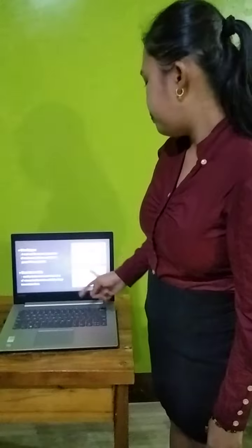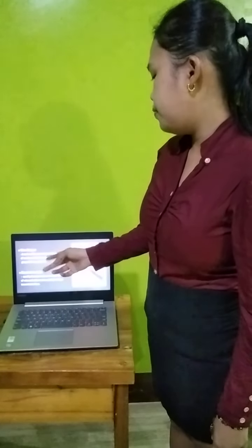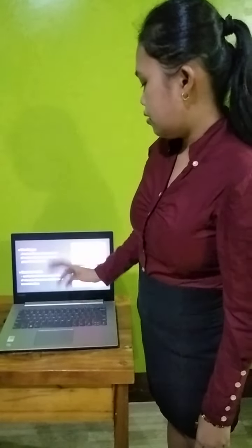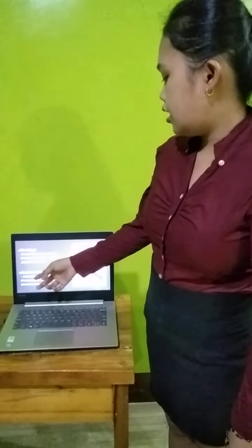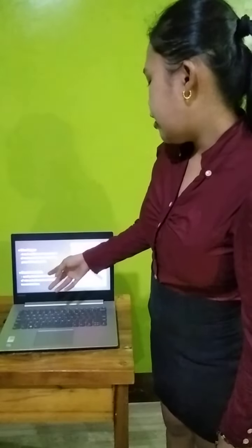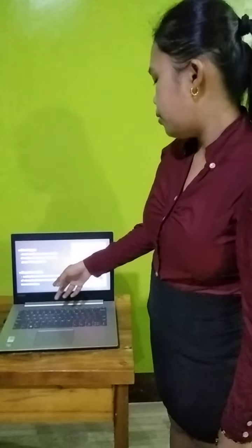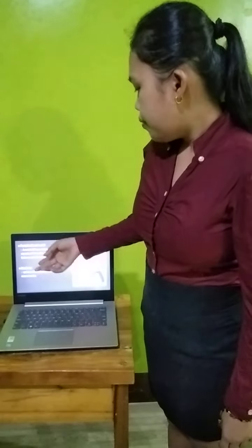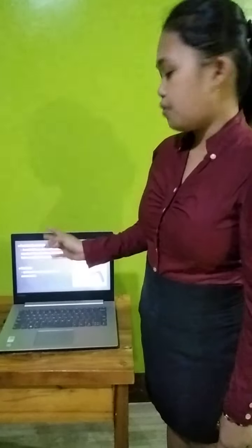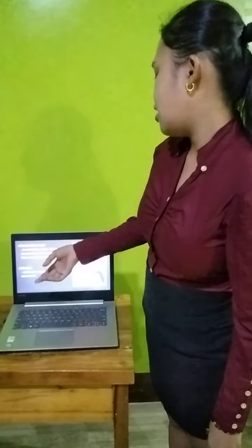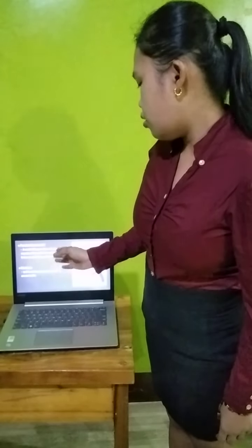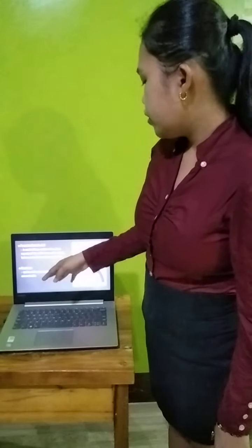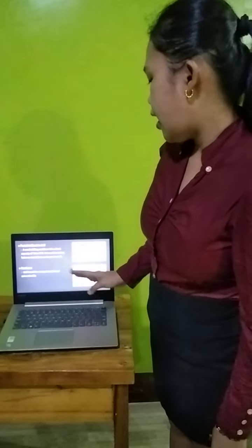Next is the wire stripper, a tool used for removing insulation of medium-sized wires ranging from gauge number 10 to gauge number 16. So next is the electrician's knife, used by linemen to remove insulation of wires and cables in low and high voltage transmission lines. Portable electric drill. This is a small drilling machine with a chuck capacity of 1/4 to 3/8. It is used in making holes on metal sheets and concrete walls. So next is the hacksaw. This tool is used to cut metal, conduit, and armored cable.